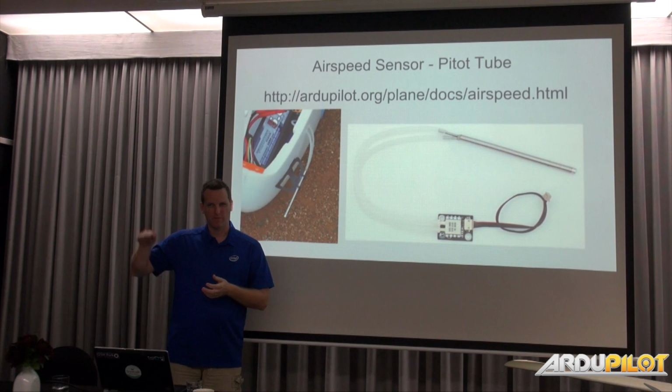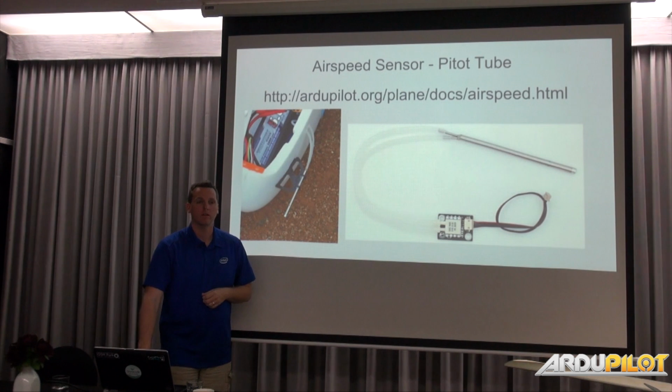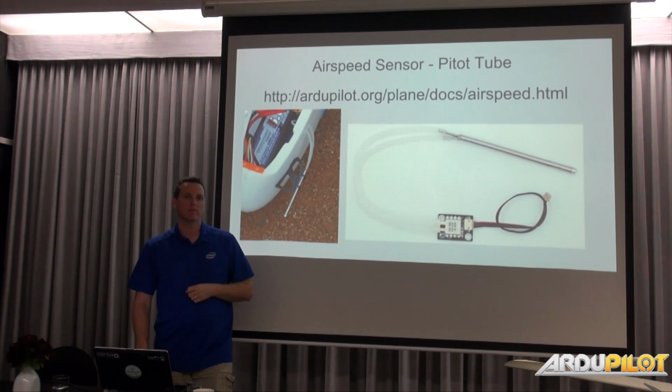A lot of people put them towards the back or whatever, that's all we want. It has to be clean air, no propellers in front of it. Just as a quick safety note on those, that sensor is very light sensitive. So direct sunlight on the sensor can give you 35 meters a second indicators.